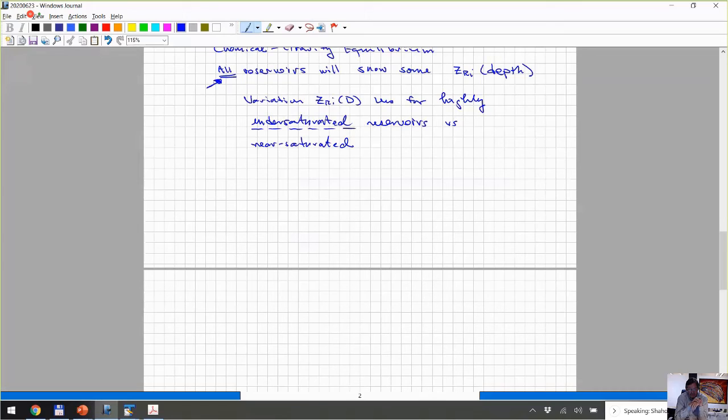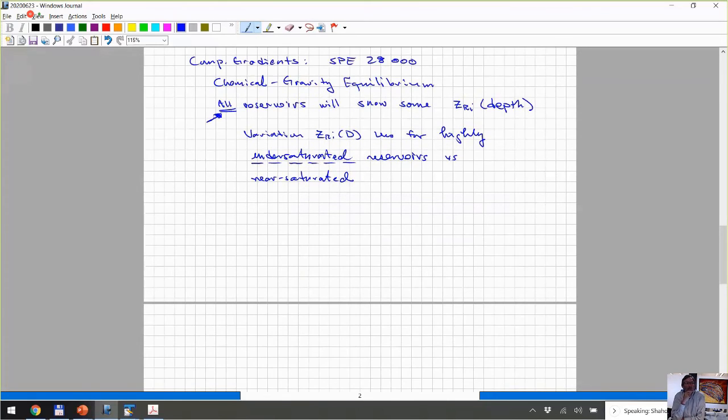But if I'm not mistaken, for example, in PVTI, if your hydrostatic pressure change with depth doesn't cross the dew point, it will not create a compositional gradient model for you. No, it will. It should. We have to use another package. It may not flip from being gas to oil, if that's what you're talking about, calculating a gas-oil contact. Well, exactly. If you don't have a gas-oil contact, it doesn't create a compositional gradient model for you. So it doesn't provide you the composition variation with depth.